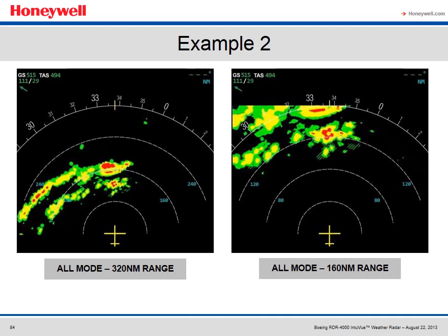On the 320 nautical mile range scale, there are two parallel lines of convective weather. The line at longer range looks rather impassable, but because the example is an actual flight test, the 757 crew will use auto and man modes to find a suitable path through the closer line. The 320-mile display gives the big picture situation. The 160-mile display gives more detail on the closer line of storms the crew will analyze to find a deviation path.